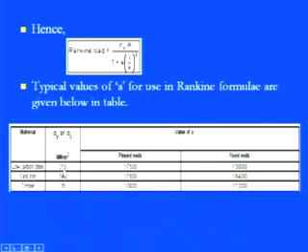We can use sigma y or sigma crushing in terms of mega Newton per meter square. So it has the clear value of sigma y, which is 315 in case of low carbon steel, 540 in case of cast iron, the brittle material, and in timber it is the least value, that is 35. Again, as I told you, the value of a depends on what exactly the load conditions are.